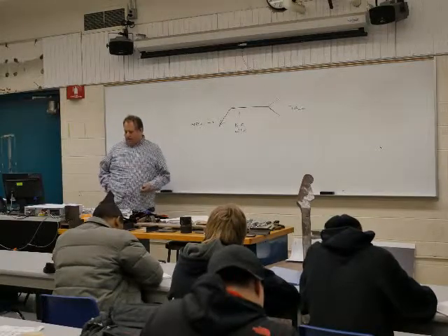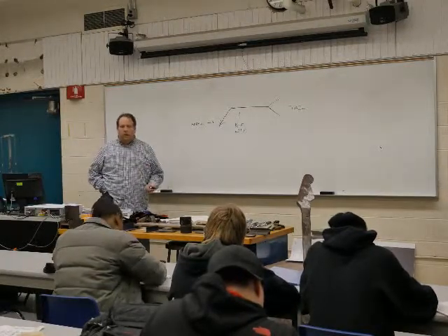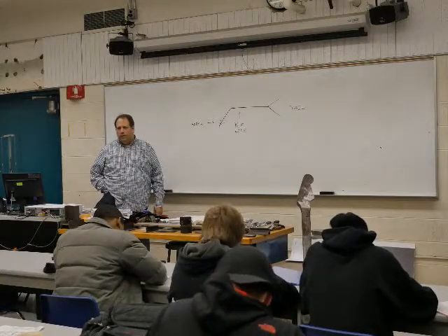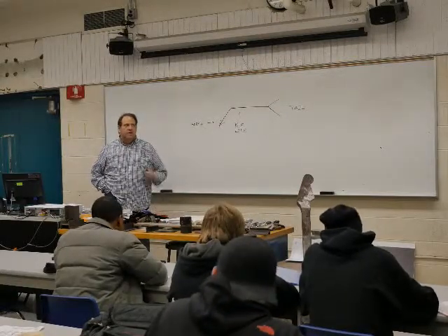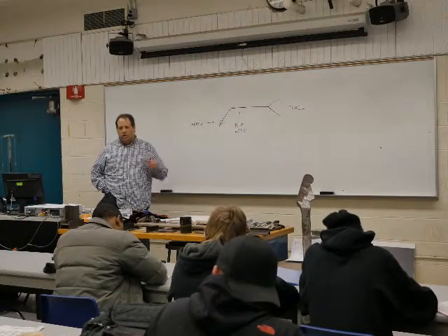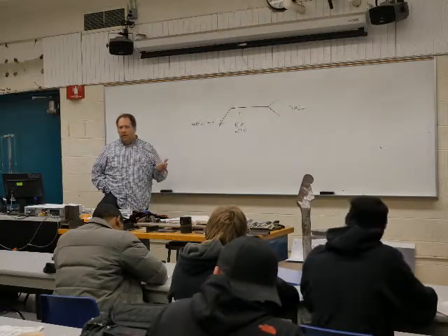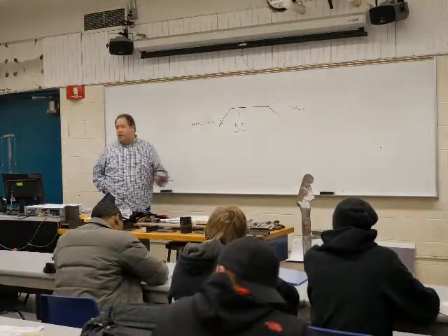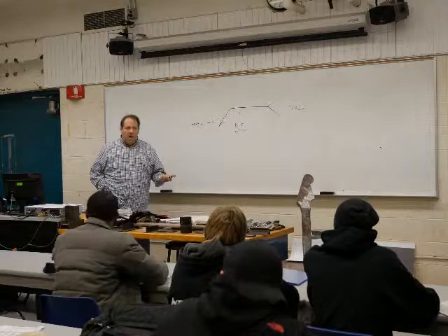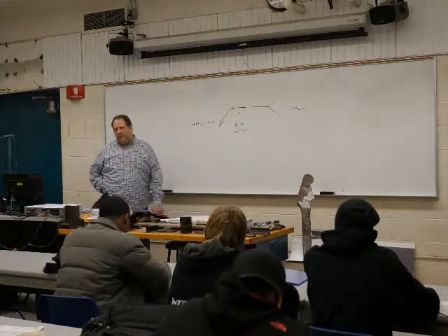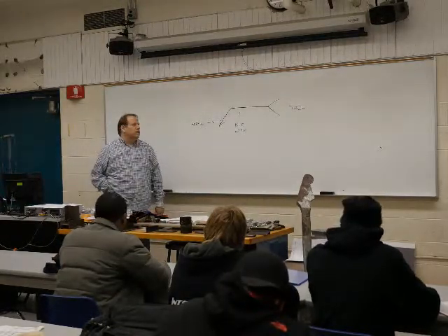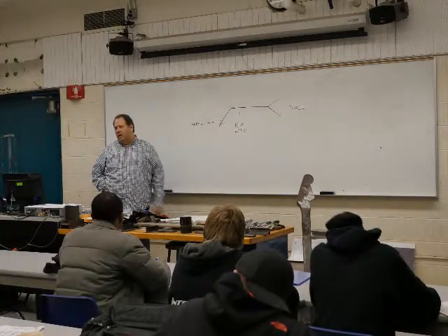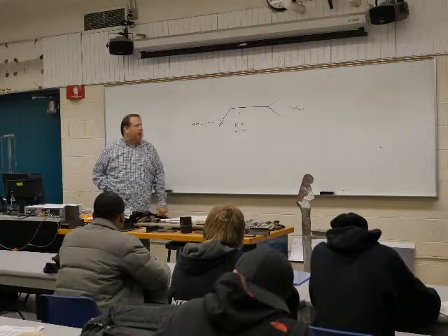Or in this particular case, everything else is stick welded, but in this one they put GTAW for that particular weld because it needs to be TIG welded. Something like that can be why we use a tail section. But other than that, really it's just for information. There's really nothing more than that. And it's not really something that needs to be decoded too much because you should have normal type of notes right in there. You're not going to have a symbol, you're not going to have anything like that.